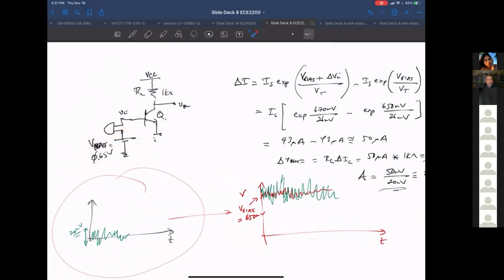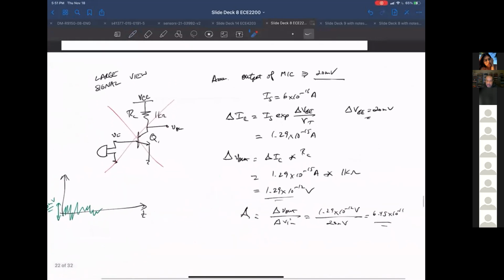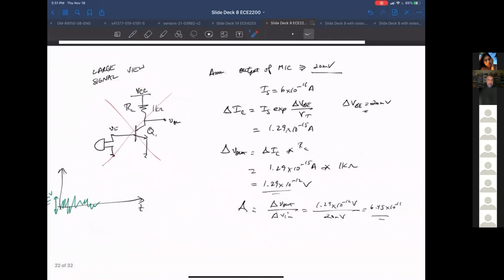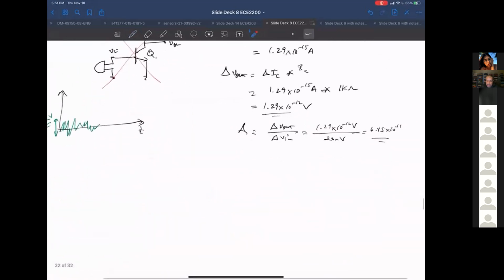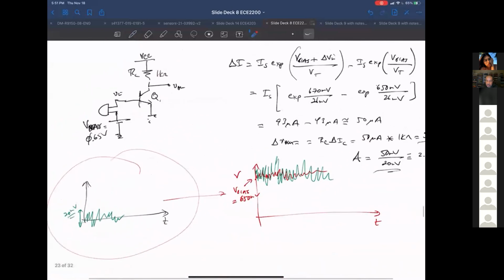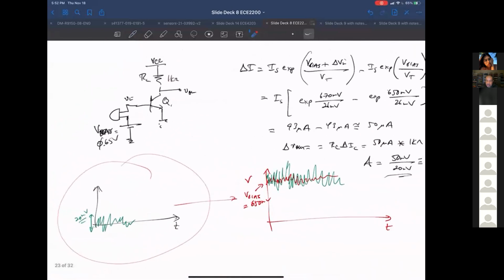Are you guys able to follow what I'm trying to say here in terms of biasing? So here we haven't biased. We get basically nothing because we don't have this bipolar transistor operating in the right region. So, don't do this. You need a biasing circuit to put yourself in a winning scenario. And this is what you like, but I'm saying this is difficult to get. Any questions about that?